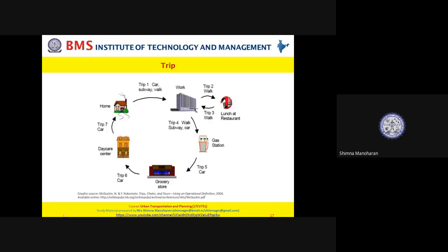So now we are seeing a schematic, a graphic representation of the trips. Here this is home. Now how many home-based trips can you find here? Anyone? Home-based trip means either the origin or the destination can be home. So how many home-based trips can you find? Yes, Prajwal? How many trips are based on home? 2, ma'am. 2, very good.